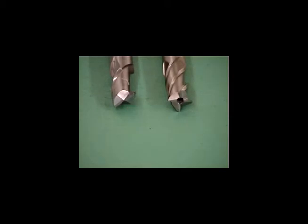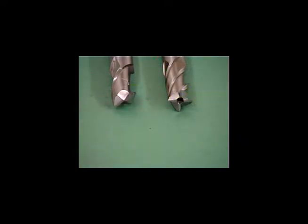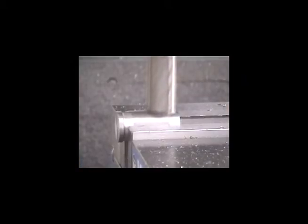A center cutting end mill, which usually has 2 flutes, has flutes that extend to the very center of the mill. It can be plunged into a part like a drill. Non-center cutting end mills have a hole in the very center of the mill. They can be used to enlarge an existing hole, but cannot be plunged into a part that doesn't already have a hole in it. Both types can be used to remove material from the part in the horizontal direction.